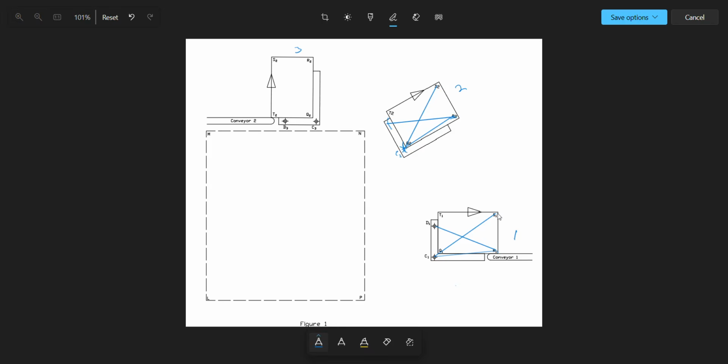And then you stand at S1 and open your compass to D1. You take that length, go and stand at S2, and draw an arc where the arc intersects the line from R2. That's where you're going to get your D2. So after getting D2, now we can start the question, because we've gotten the attachment points for position 1, position 2, and then position 3.